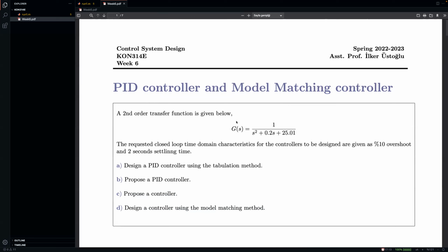And we are adding poles and zeros to it, so it is a high order controller method, and it comes up with high order controllers. For this case, it was a second order controller, which is okay, but most of the time, if you have a fifth order system, for example, it would need 5 zeros to cancel out these poles. It's quite interesting to think about that.